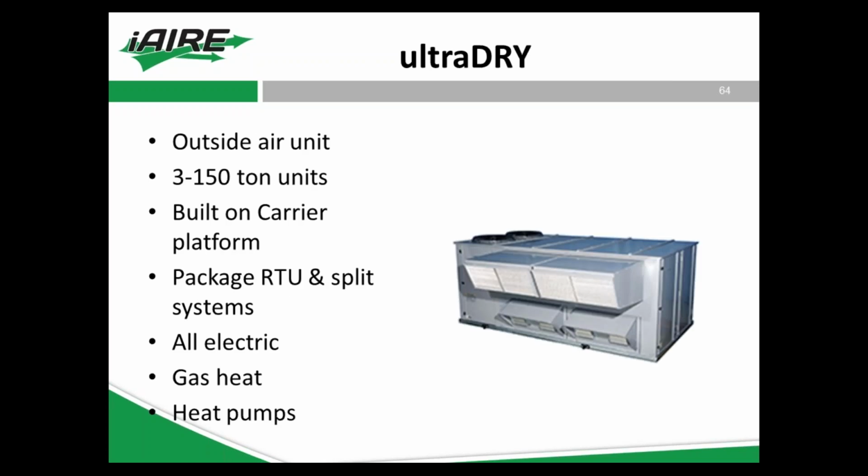So I'll start with basically their bread and butter, which is their standard DOAS unit, which is called their ultraDRY. So this is ranging from anywhere from 3 tons to 150 tons, and it's built on the Carrier platform. So I said this earlier, but the Carrier units that you may or may not be familiar with, the RTUs are the TC, the HC, the LC, which are different package units between 3 and 30 tons just based on efficiencies, and then also their larger units, which would be the A series, the P series, and the N series. And iAIRE works with them and modifies all of those units.